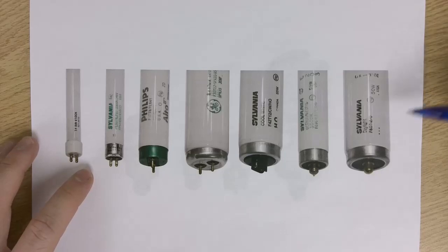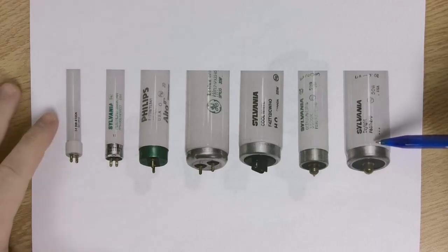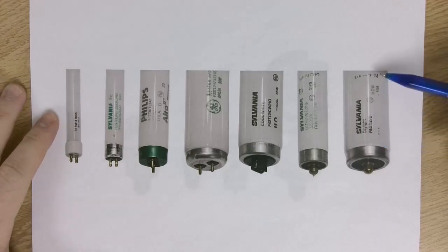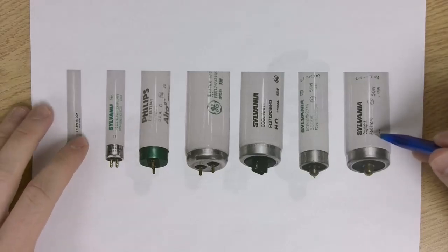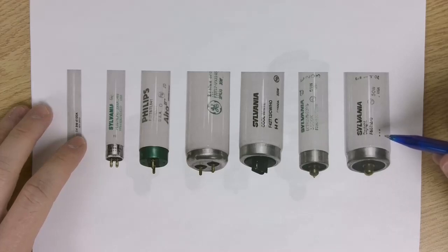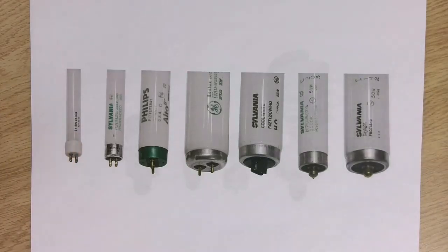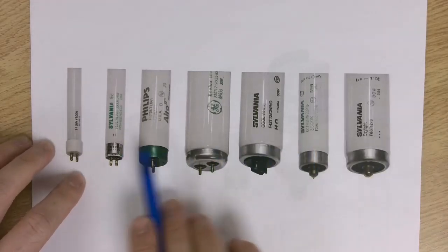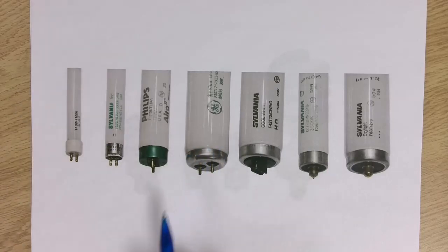So now we don't have a filament that's putting off heat, which produces light. Now we're igniting a gas, which produces light and some heat still, but now we're far more efficient than a halogen or an incandescent. But the problem being now we have a ballast. So now there's some extra components. Usually when you see these bulbs or these lamps acting funny, usually it's a bad ballast.